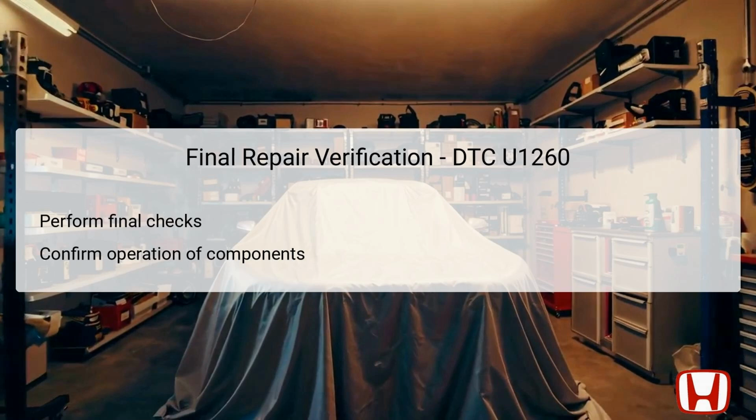Also, it's important to recheck for any DTCs using the HDS to confirm that no further erroneous codes are triggered. Only when all tests yield positive results should the vehicle be considered ready for normal operation.